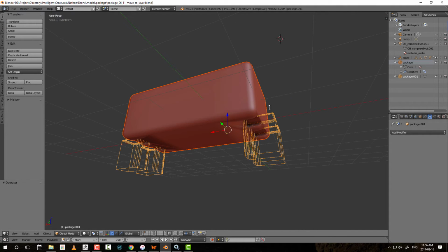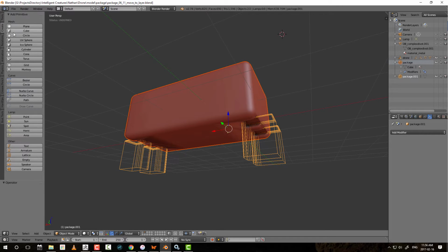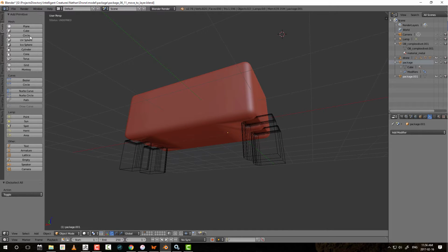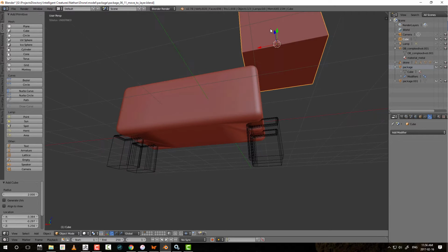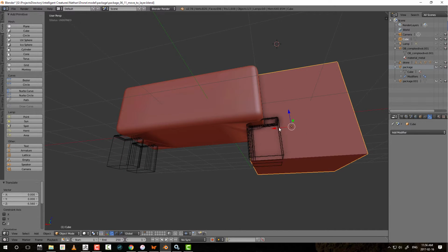Okay, so far what we've done is only a subtractive layer, but now I want to add to this object, right? I want to add some bumps to this. So you know what, let me just very quickly press A to clear the selection here, make a cube, and position this cube into place.